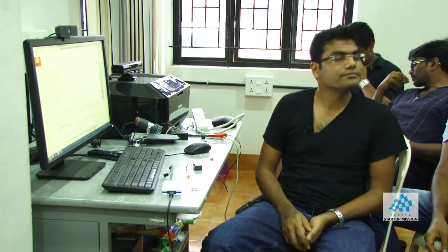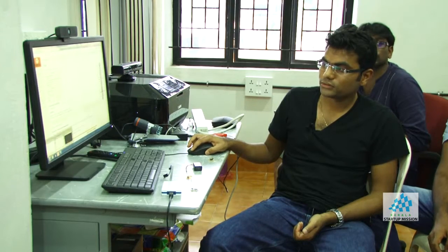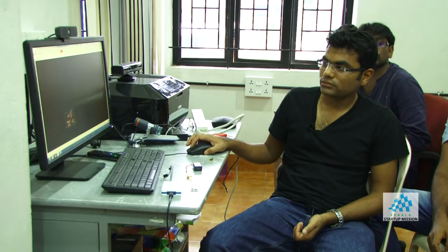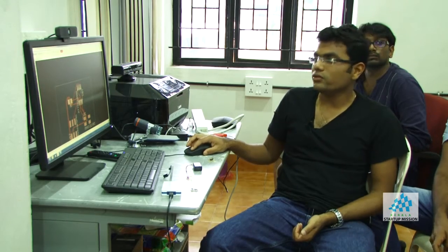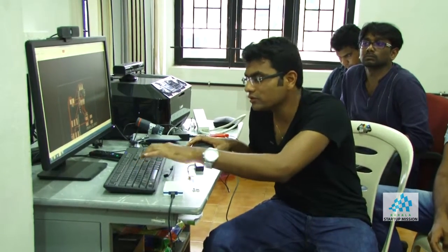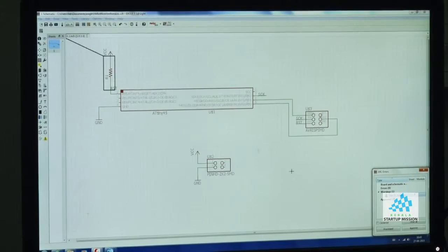Okay. In Eagle, how do you do the ERC check? Can you do the ERC check in Eagle? Yeah, you can. Yeah, you can do ERC. I think it's ERC, and it tells you about the connections.